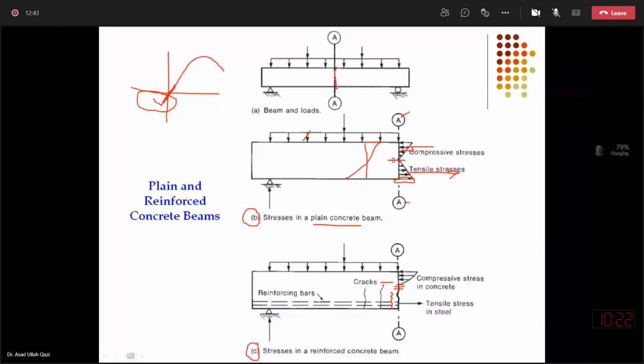width and length are visible, always above the tip of the crack there will be the neutral axis, because a tension crack cannot enter the compression domain. So in this picture we can safely consider that the neutral axis, because the crack is present here, will be almost over here at the tip of the crack. Above it is the compression and below is the tension. Since it is reinforced concrete, the concrete contribution in tension is very small, so we are going to neglect it. So entire tension